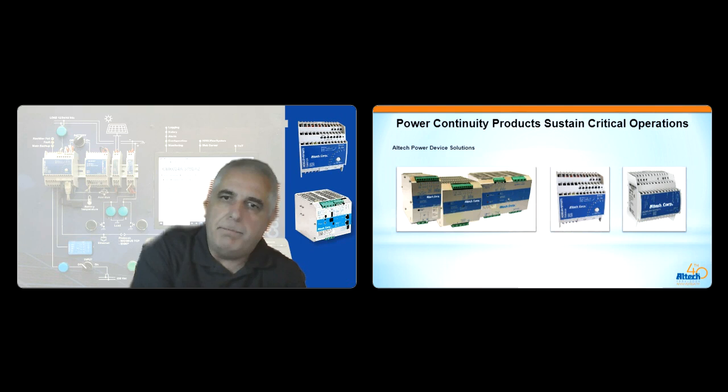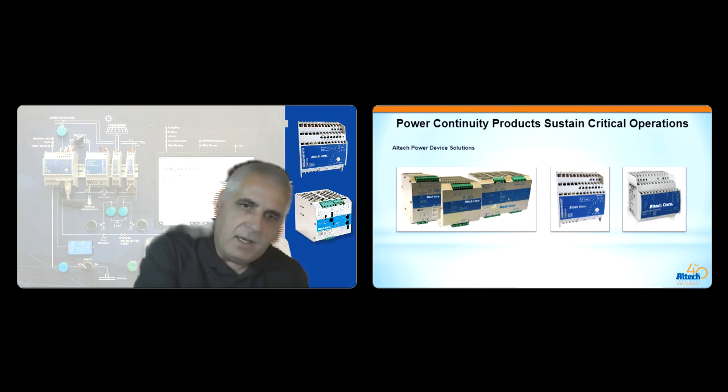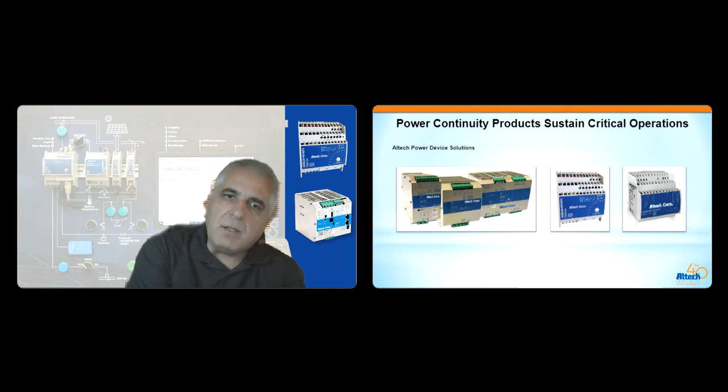Obviously, a lot of times, budget is a critical requirement. So when you are choosing a UPS, look at the total cost of ownership, TCO. Consider the initial purchase price, installation cost, and ongoing maintenance expense when evaluating a UPS option. Calculate the TCO over an expected lifespan.